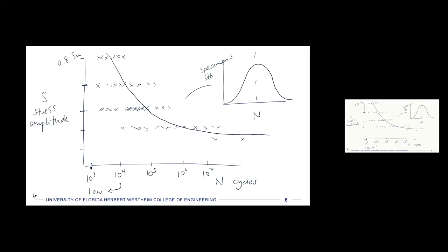But if you want to go one step further, and this is kind of what I talked about, there's this window of failure. You can put a series of curves on here that have to do with reliability, right? So if you remember from statistics class, there were often problems like: I've tested 100 things at exactly the same conditions, and I got a distribution like a normal distribution. If I subsequently measure one additional measurement, what is the probability that it would fall within X domain? Like within 1 standard deviation, within 2 standard deviations, things like that. And so those reliabilities can be used to generate a family of curves like this.